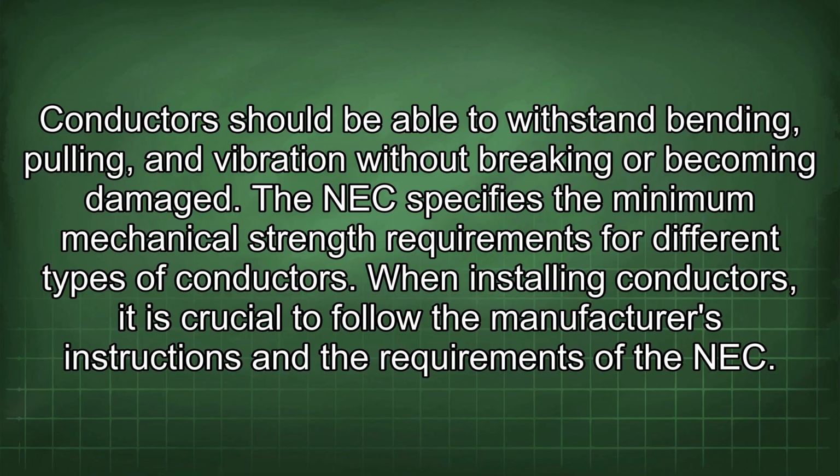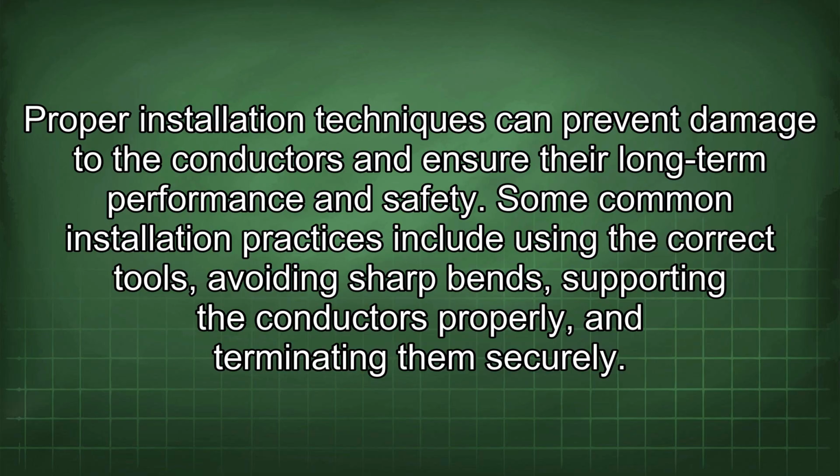When installing conductors, it is crucial to follow the manufacturer's instructions and the requirements of the NEC. Proper installation techniques can prevent damage to the conductors and ensure their long-term performance and safety. Some common installation practices include using the correct tools, avoiding sharp bends, supporting the conductors properly, and terminating them securely.